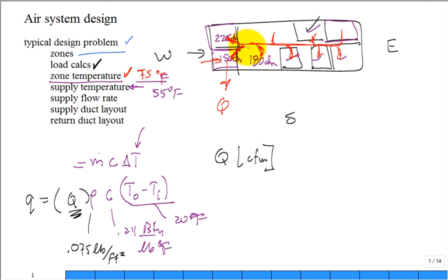It doesn't stay around very long. They take it over a rafter run, and what does it do? That round duct kinks pretty poorly. Think about the airflow through that. You think that's a uniform cross-section?